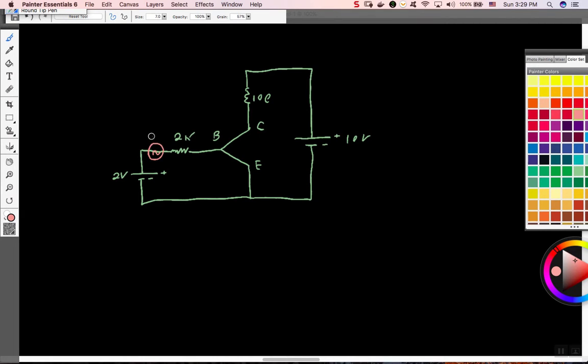So you can think of this one as a signal that we want to amplify. So we have some AC source, maybe it's music or radio or whatever it could be, and we want to amplify it. And the question is, how do we analyze it? Here we can see that the two sources have different frequencies. This one has some frequency above 0, obviously that's an AC source. This one is a DC source with a frequency of 0, so we cannot just add them up together.